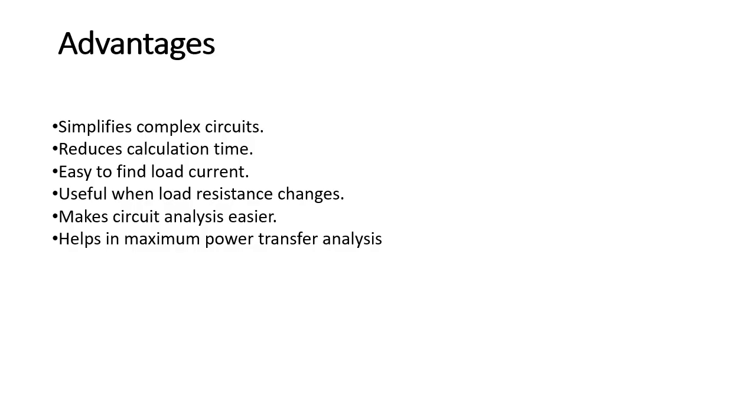When changes in the load resistance take place, this theorem is applicable and helpful. It makes the circuit analysis easier, and it helps in the maximum power transfer analysis. The maximum power, Pmax, can be found out on the basis of this Thevenin's theorem.